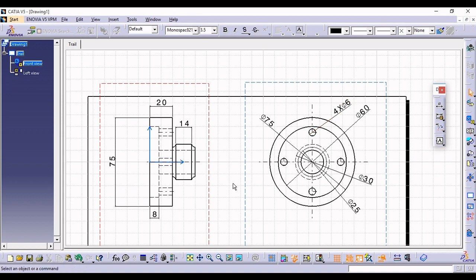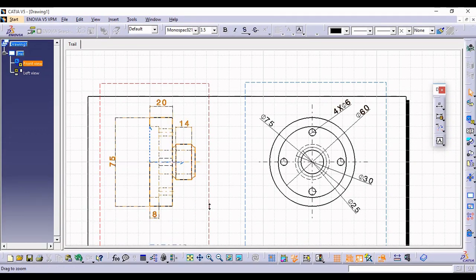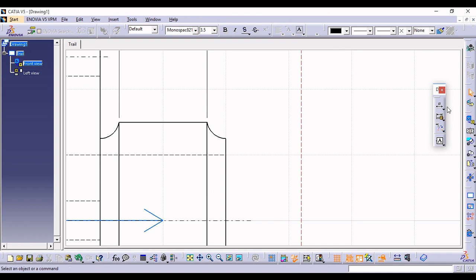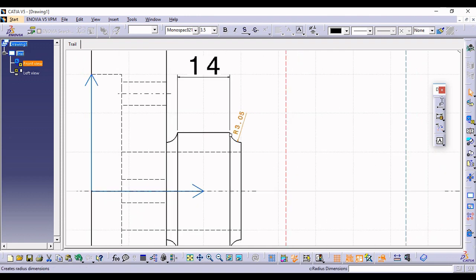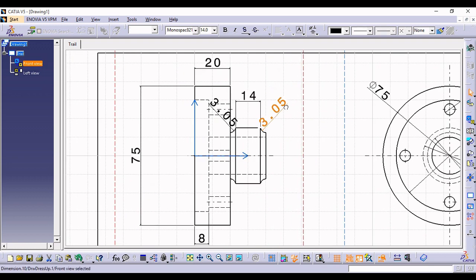So in this way you can make use of the dimension line as well as the extension one. Similarly here, radii are there, so we will assign the radius here, go for the radius, yeah, okay. Similarly here also we'll go with the radius, yeah, fine. Again, these two are so small, so select 1, 2, go into apply properties, and here, yeah, fine. Now in this way we can come up with the same.